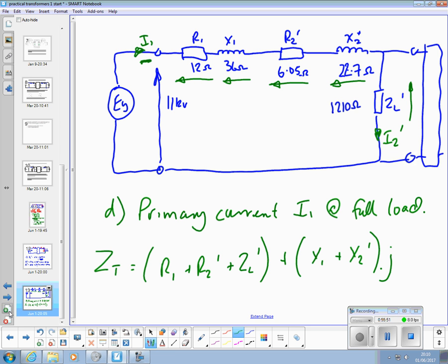So I kind of jumped a step. If that's really causing anybody any problems, say so, and we'll do it individually. But that's effectively what you'll do. The three resistors are pure resistors, and we just add them up, and there'd be no j parts associated with them. The two inductors are inductors only, so they'd have no real part, but they'd have j parts. So we just add the resistive parts together, the inductive parts together, all in one go. Anyone really struggling with that concept?